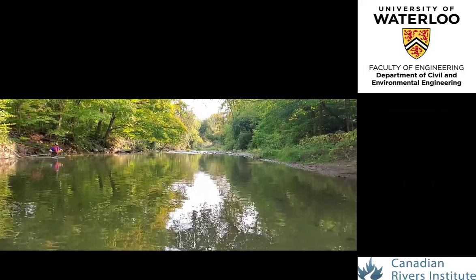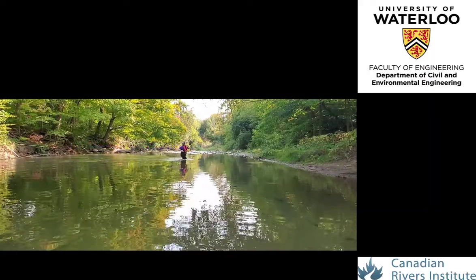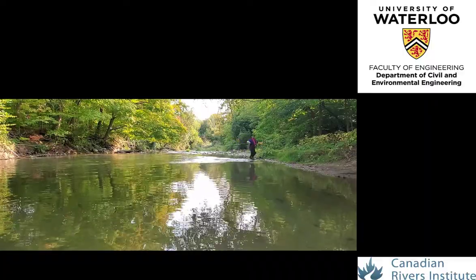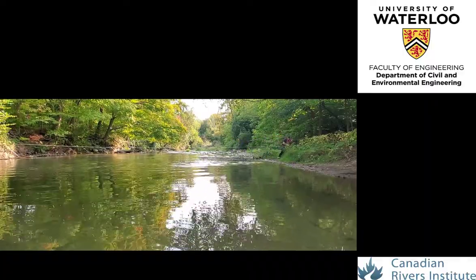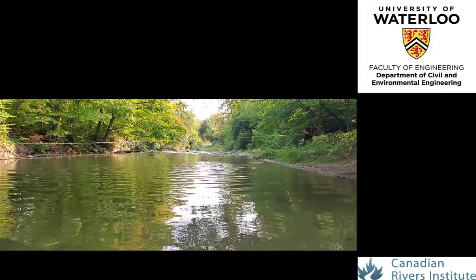The first step is to span the tape measure across the channel. It is known that the tape measure does not need to start or end at the water's edge. For convenience, here, the tape measure spans further on both sides of the channel than the water's edge and is secured into the ground with metal pins at both ends.